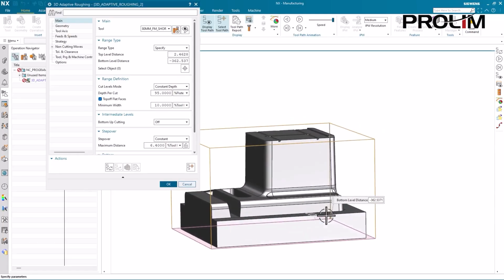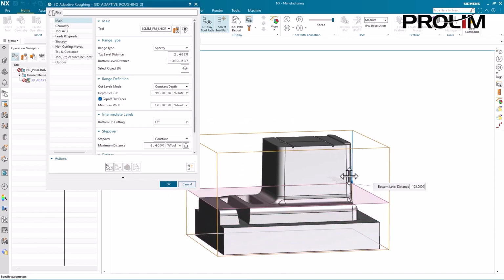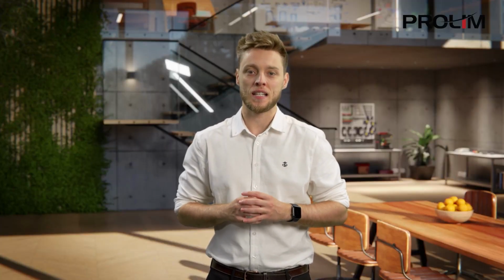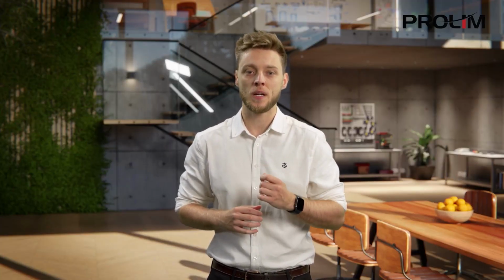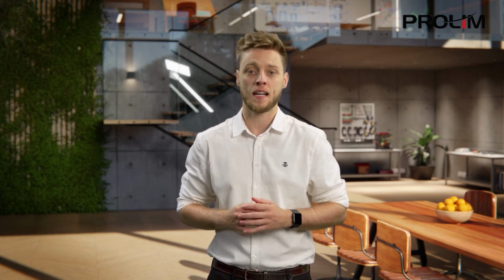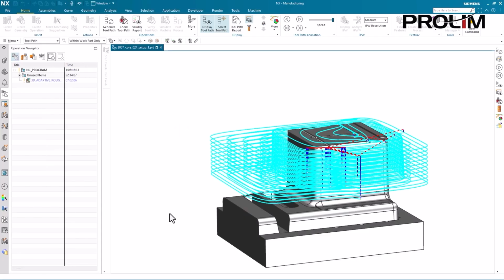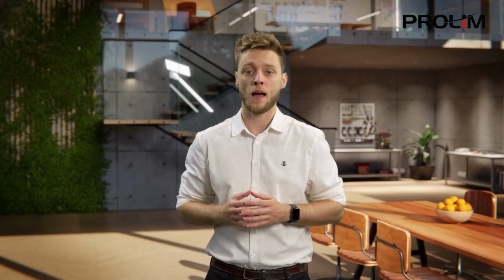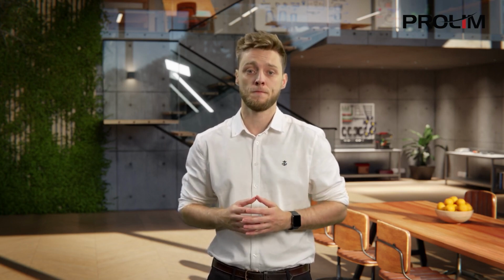We can either let the system set the range automatically, or we can specify our own custom ranges by dragging the slider bar. We've really focused on reducing the time taken to generate the high-speed machining toolpath with 3D adaptive roughing. And this is how our mold looks once the roughing is complete. This ultra-fast roughing method can reduce machining time by more than 60%.